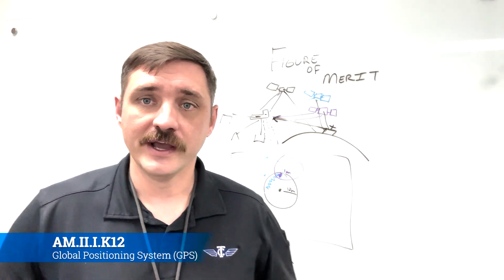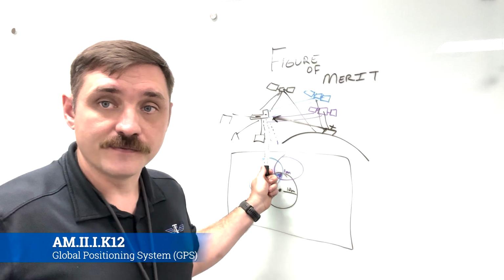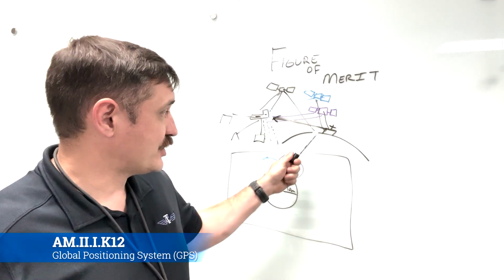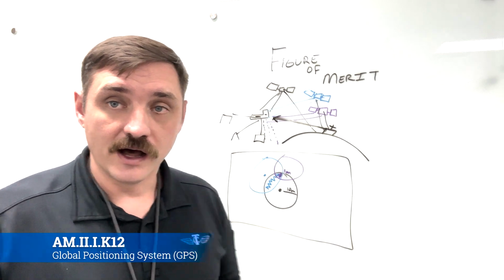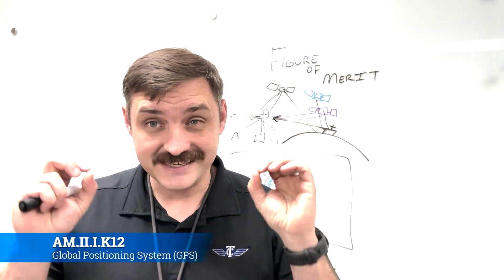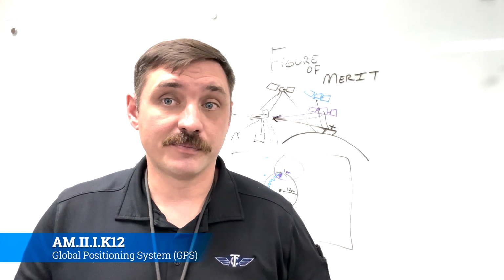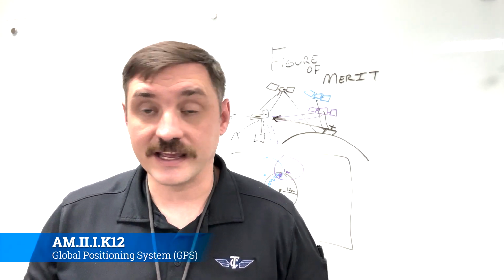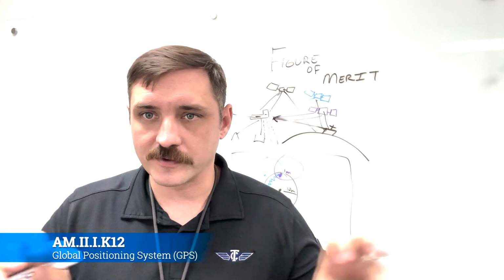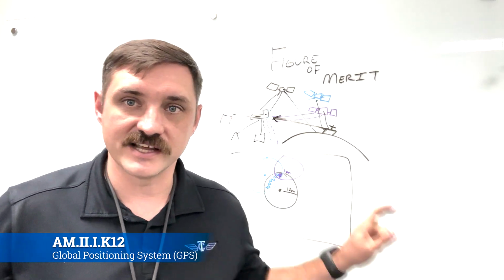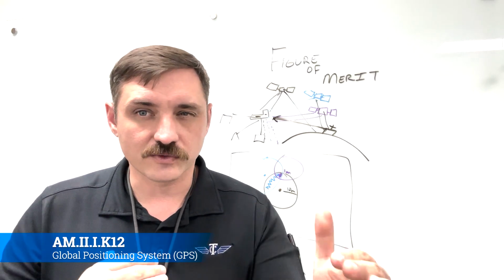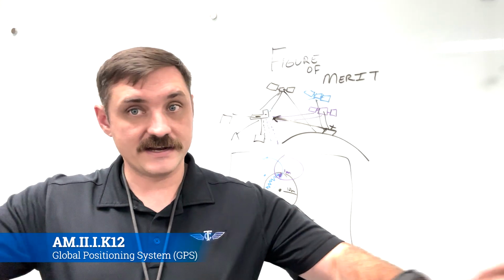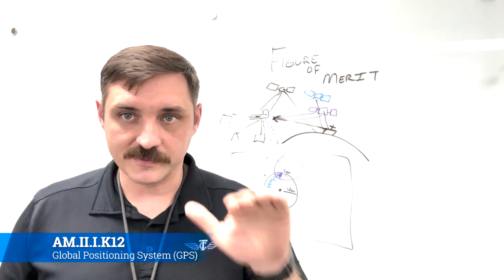All it comes down to is increasing the number of data points that the airplane can draw from to know where it's at, and correcting this figure of merit problem so that the airplane knows exactly where it's at. This is the pretense, or the foundation, for things like autoland. It knows as it comes in. It's drawing from a bunch of different systems, but one of the primary ones is that it knows within about 1 to 3 feet where it's at above the earth, and it would not pay attention to anything else, just use GPS WAAS to come in and land.